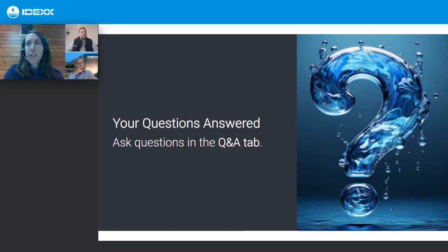I guess we can see it through the head loss in the filter. So particularly when we have dirtier, and I want to put in inverted commas dirtier, because we actually, as I said, have had very few detections of protozoa, and our turbidity is, I think, like 2 NTU, which is pretty clean. But we can see the impact on head loss, and we don't really want to be getting closer to our terminal head loss where we're backwashing on head loss.